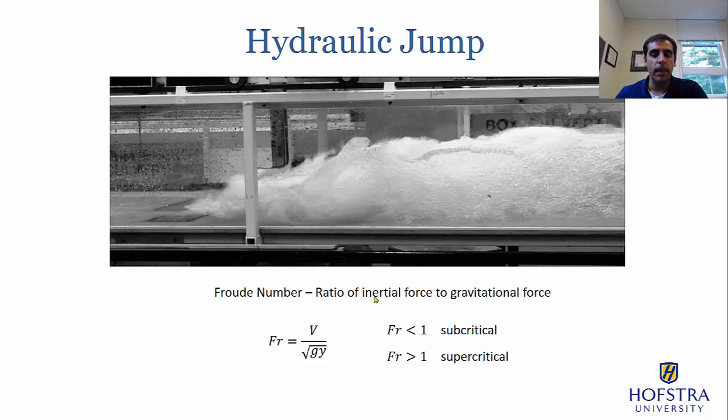So what happens is, upstream, we're going to lower a little gate, which is going to force the flow through a small area, giving us a high velocity jet, like this. Then we're going to have a tailgate back here that we can raise or lower, and that's going to cause an obstruction. The flow is going to have to adjust to that tailgate and slow down.